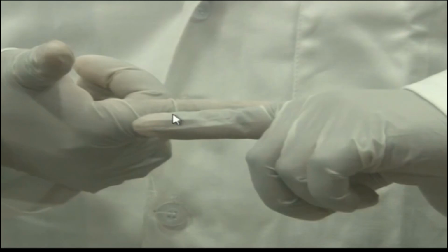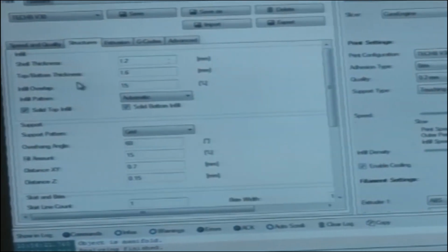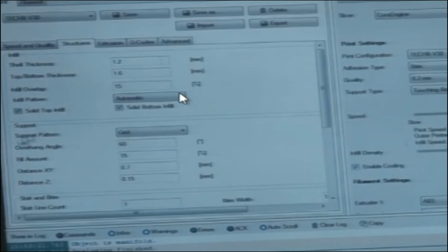So this is kind of an overlap. The second layer wouldn't be exactly on the top of the first layer, it will be a little overlap. In this case, you can just see like the fingers, we are just trying to demonstrate that 50% of overlap can be seen here, but 15% of exact overlap would be there if we put this input in the machine. So this bead is deposited in this way. Sticking the layer would not be proper if this overlap is not there.